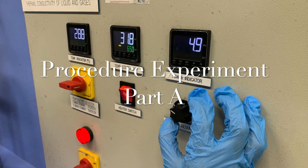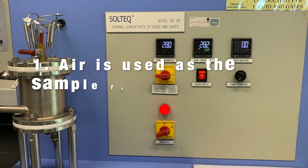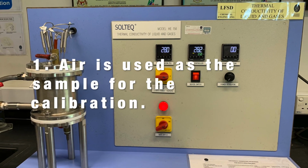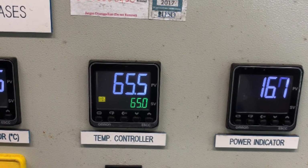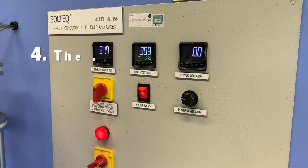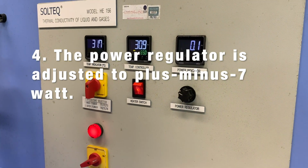Procedure for experiment part A. Air is used as the sample for the calibration. Make sure the temperature controller is set to 65 degrees Celsius. The heater switch is turned on. The power regulator is adjusted to approximately 7 watt.